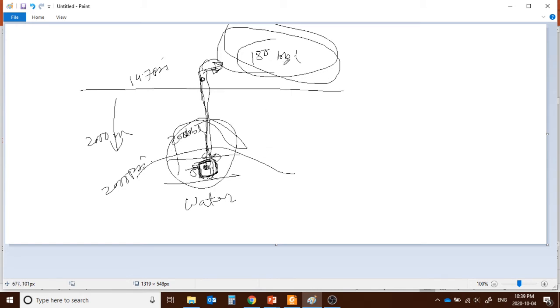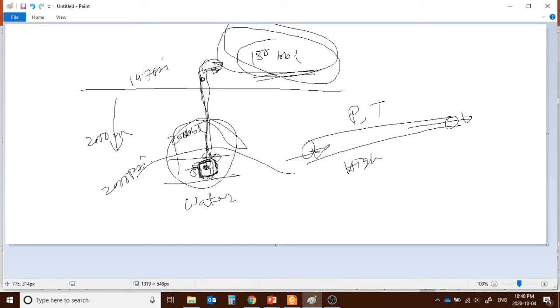Another very important thing is, when you take out the oil, after that you need to transport it through a pipeline. When you transport it through the pipeline, you have to maintain a certain pressure and temperature. Sometimes this transportation happens at very high pressure, and if the pressure decreases or you increase the temperature, then inside the pipeline some bubbles could be created, and these bubbles could severely corrode or erode the whole pipeline system. So this is one example.